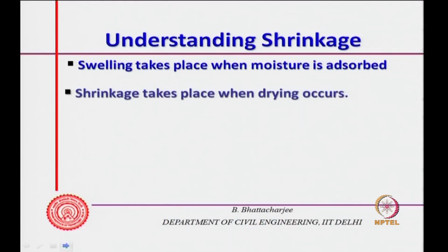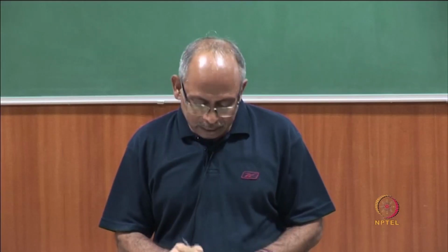At this smaller R, the compressive forces generated onto the skeleton would actually compress the system, right. It will compress the system, surface tension will change, and it would compress the system more. So, there is a compression because of the capillary itself. There is also compression because of the adsorbed water being withdrawn. So, this results in drying shrinkage.